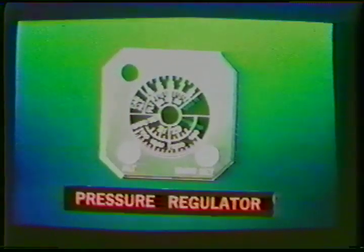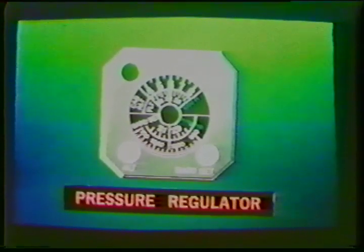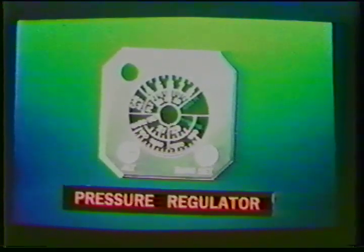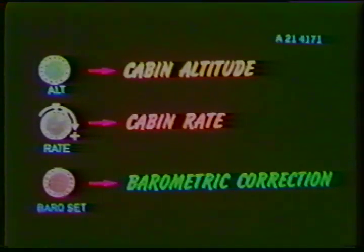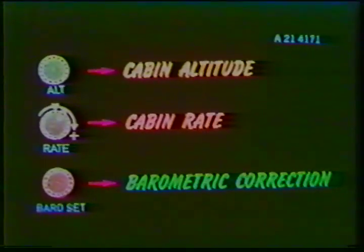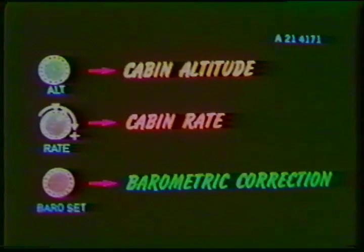Management of the pressurization system is accomplished with a cabin pressure regulator and with other input signals. The controller transmits an electric signal which actuates a motor on the outflow valves. The 3 rotary knobs mounted on each pressure regulator are for setting the cabin altitude, the cabin rate of change, and the barometric correction.